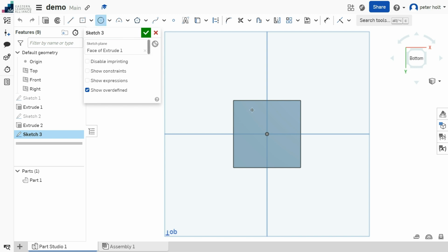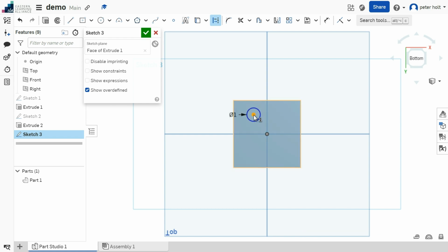And this time I want to draw 6 identical circles. But you know, the computer's going to have a way to pattern these really easily for me. I'm going to make these 1. That's going to be the right sort of size for me. And I want 6 of them. Before I do that, I'm going to position it roughly in the right place. So I'm going to press escape on the circle tool, so I'm back to having a white selection tool. And I'm just going to move that in using the touchpad on my computer and move it into where I think it will be about the right position. So about there. Okay. Having moved it, I'm happy with the position.